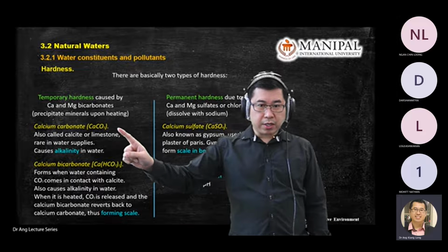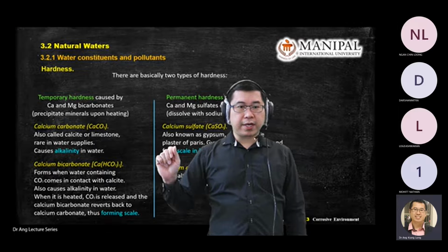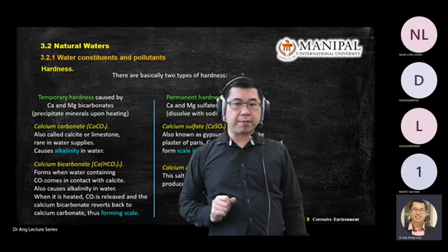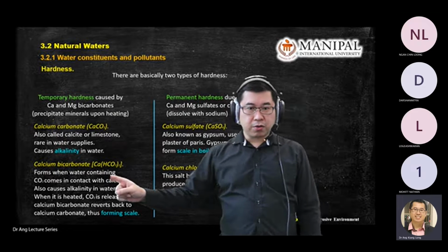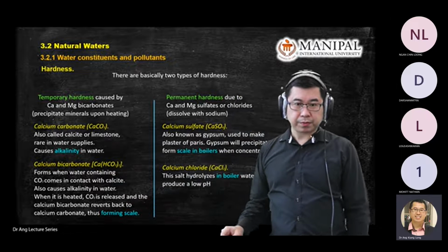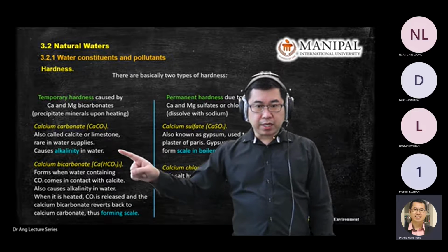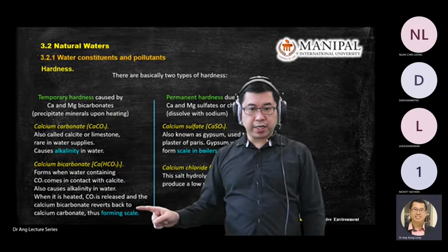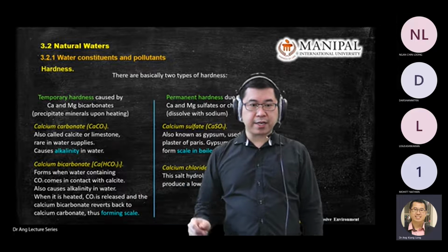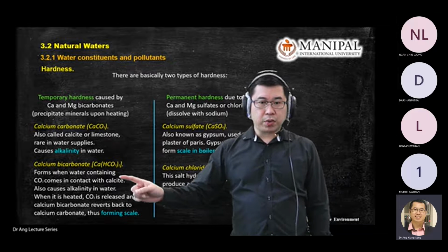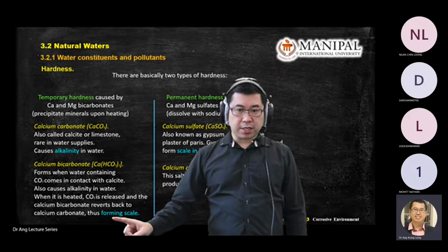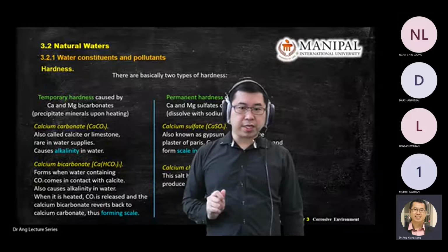And then I've shown you before in our lecture how calcium carbonate becomes bicarbonate. There's a process there. So when you have calcium bicarbonate with this equation, this calcium bicarbonate actually forms a scale. This is the thing that you can find inside the water pipe, maybe a little bit of white powder. So this is the product that you will see in a pipe.